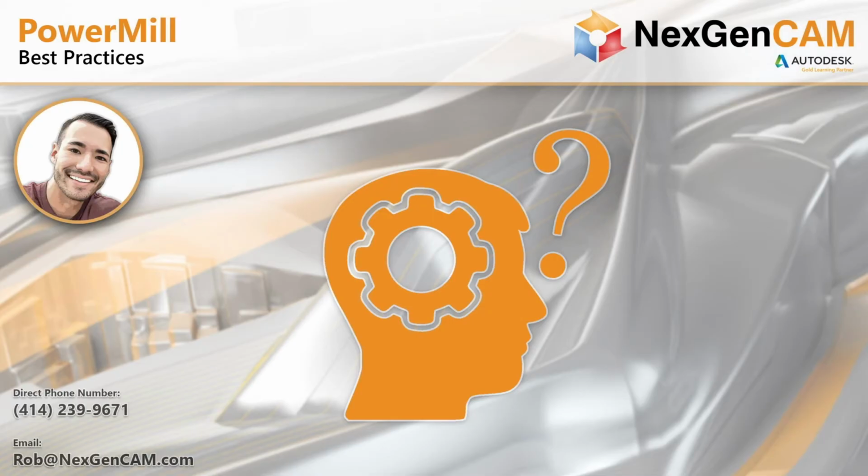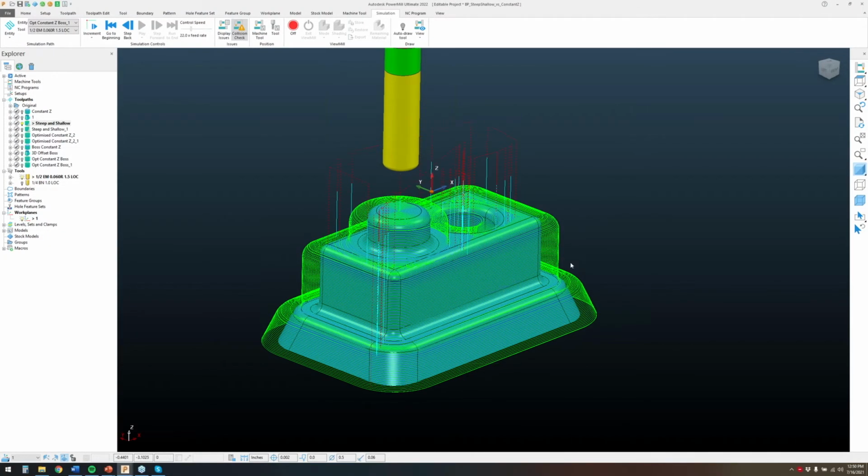And Dan is asking, is there a way to have different lead ins and lead outs in the shallow part of a steep and shallow toolpath? So we have a steep and shallow toolpath, and he's looking to say, hey, on your shallow areas, can you have a different lead in, lead out than in those maybe steep areas? So normally with that, since this is one toolpath, if we were to do a lead in, lead out, it's going to do that lead in and lead out for the complete toolpath itself.